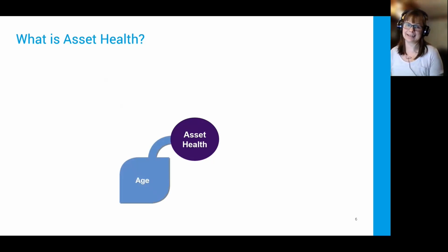What goes in there is essentially an age, and this is an important component. It's useful when you don't have a lot of data. When you've got assets which you haven't got a lot of condition information on, it helps get us started. But the principle behind common methodology or CBRM, which we use, is that they are age modified by condition. So we do start from age, but we modify that by condition. So we're saying that you'll never condemn an asset, or you'll never have an asset with a very high health index, until you know that you've got some condition issues with it.